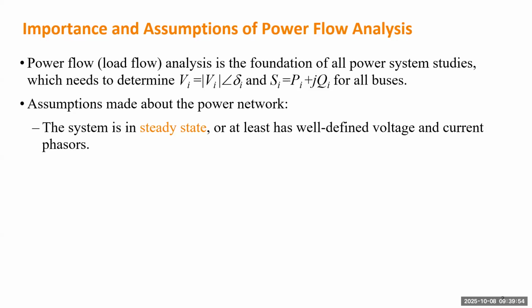So the requirement will be, ideally, you want to have the system in steady state. If it's not perfectly in steady state, it needs to at least have well-defined voltage and current phasors. So that's a bottom line requirement. If you have well-defined phasors, you can utilize all the methodologies and models we're going to talk about in this session.